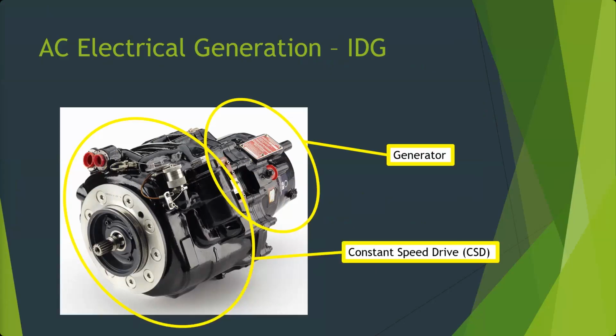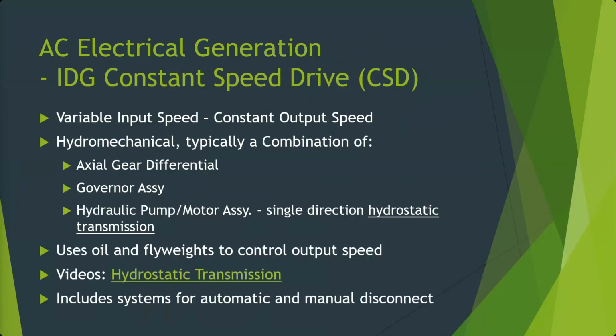There's a whole bunch of tubes that all run to the bottom of the engine. It's called a gang drain. They all gang together, and you'll get oil dripping out of that. So you'll see it on the ground essentially. You'll see it dripping out of the gang drain.